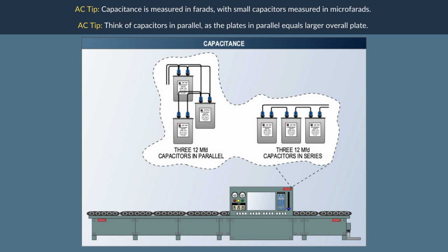When a capacitor is connected in series with an alternating current circuit, the current is allowed to flow back and forth in the circuit without actually passing through the capacitor. Notice, the electrons build up on one plate of the capacitor and flow out of the other plate. An electrostatic field is established that causes the current to flow in the opposite direction. However, as the voltage from the source begins to drop, the electrons start to flow away from one plate of the capacitor and onto the other plate.